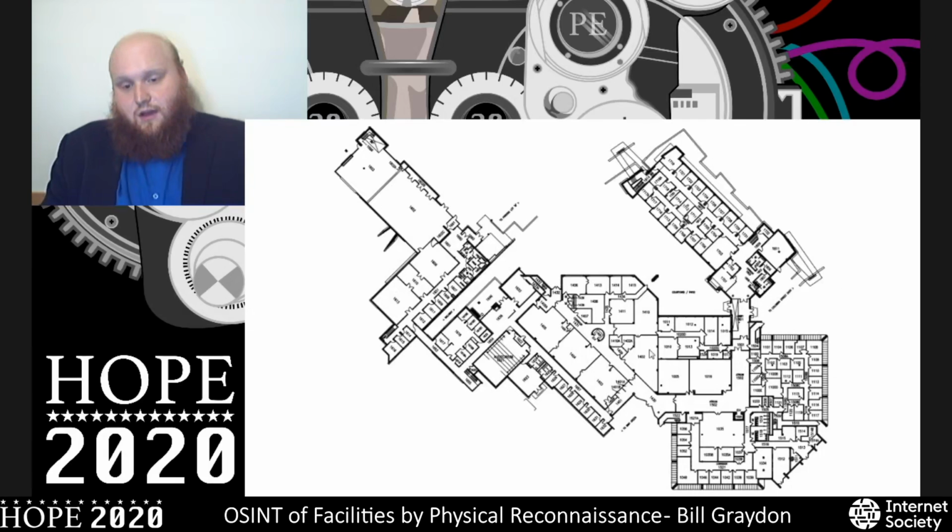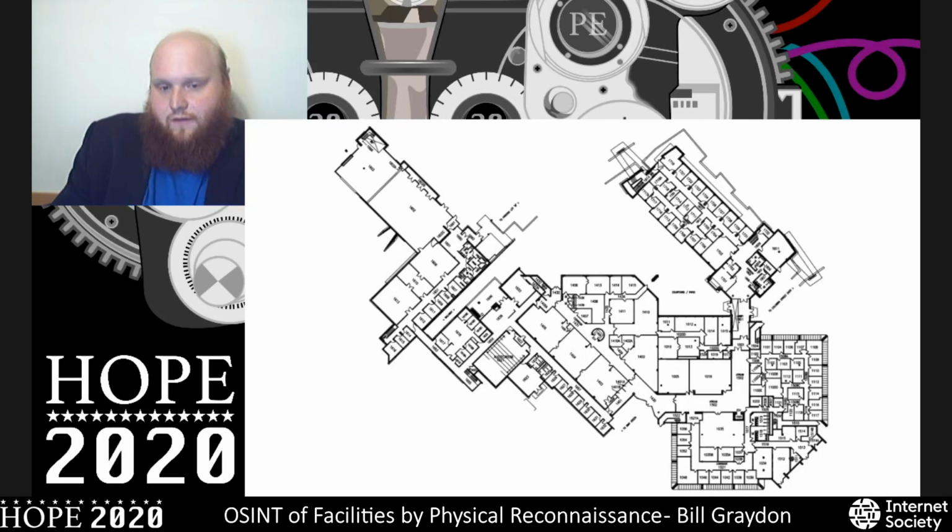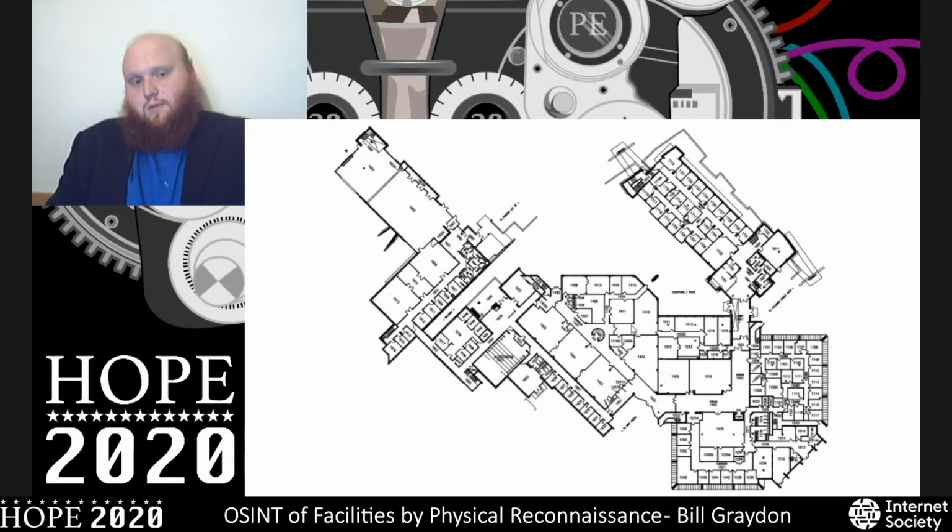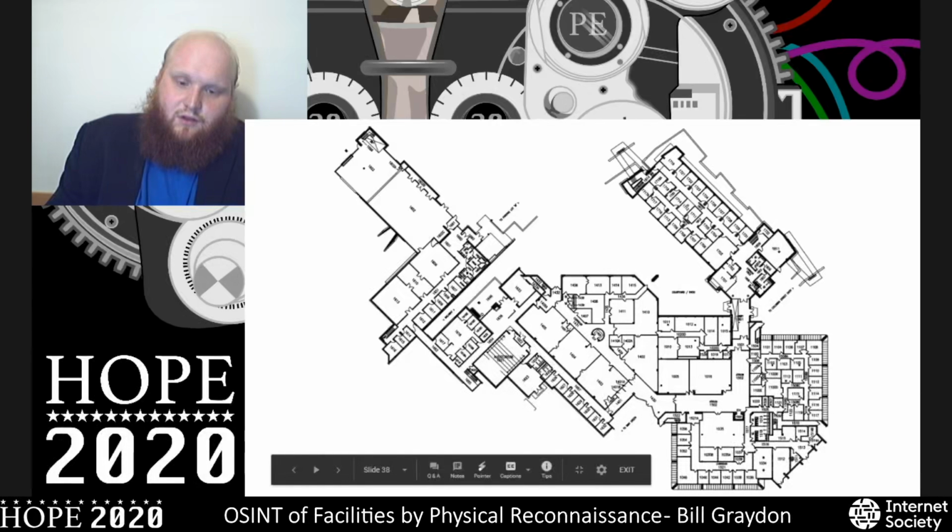Here's an interesting case where we have 45-degree angles that would be visible in the exterior massing, which generally means that we have two different orientations of halls and rooms on the inside. Where do they actually make that transition? Well, we can tell based on circulation requirements. So in this case here, this green boundary, so to speak, between the 90 and the 45-degree angles, it can't really continue on over here because it hugely interrupts circulation.